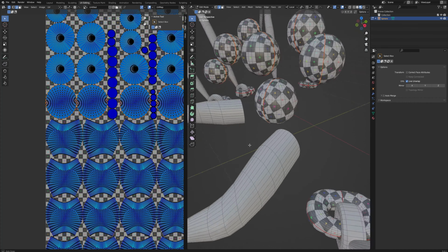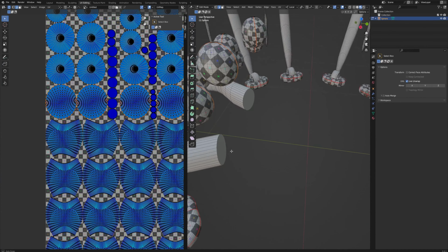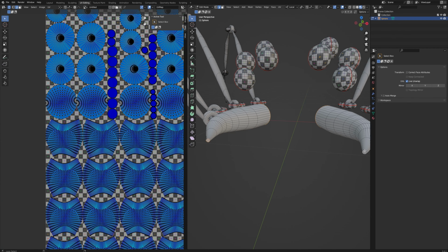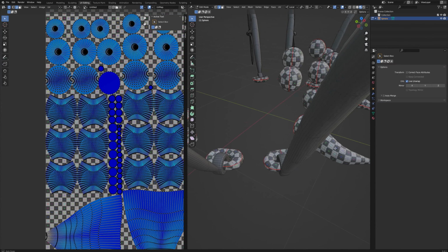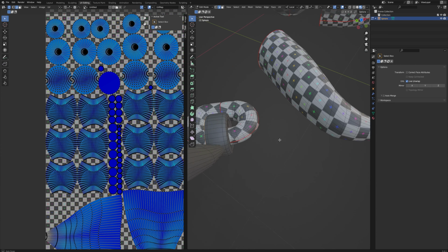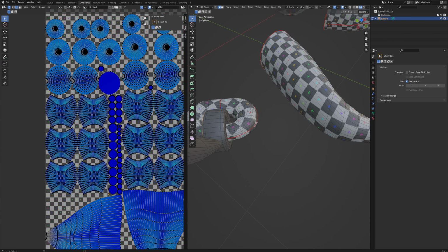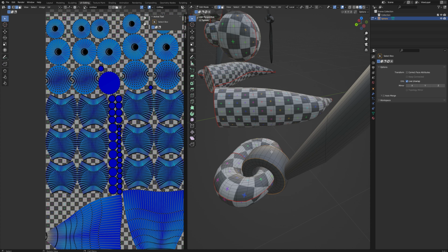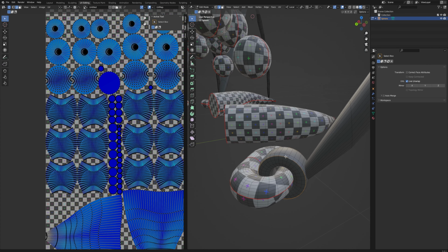Now for something like this, which is closer to a normal cylinder, we select the bottom face and the top face, and then just one line connecting the two of them. And we unwrap that, and the fangs are also unwrapped. And for these little buggers over here, that's going to be a little bit more interesting, because we need to select this edge over here, as well as this edge. You can select an entire edge loop by holding Alt down, if I hadn't said that already, by the way. Only if your topology actually flows well though, which in my case is about half of the time.